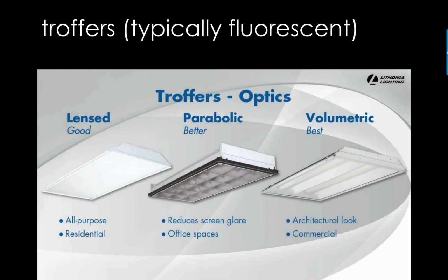Troffers are another type of light source you're going to see a lot of. Obviously, these are super duper exciting, as you can imagine. These are obviously more workmanlike. The big decision you have to make is, do you want the cheapo, open look, which some people call the architectural look, especially if they're shielded with a sort of reflector. Parabolic light sources have very good cutoff angles. They are a little bit lossy in terms of you lose a lot of energy with those.